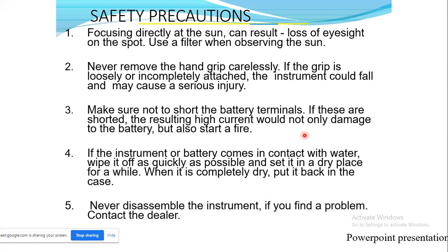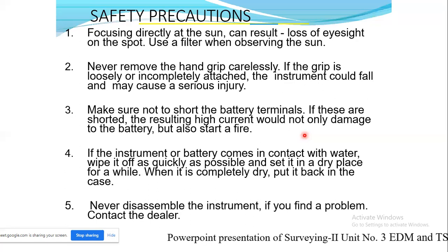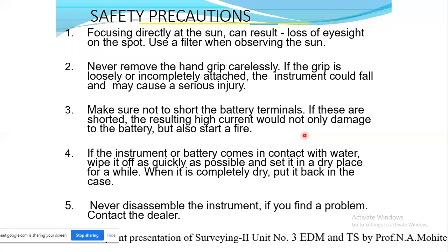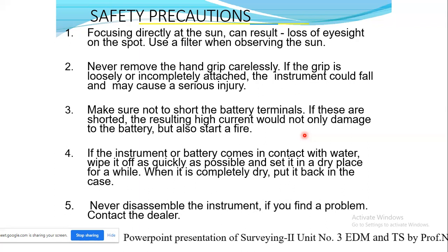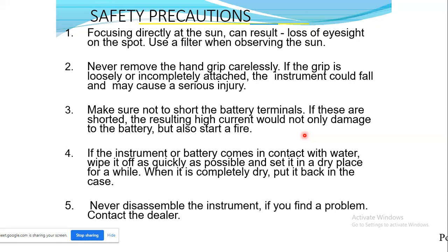Never remove the hand grip carelessly. If the grip is loosely or incompletely attached, the instrument could fall and may cause a serious injury. As I told you, it is a heavy one. One person is going to handle the instrument, and the second one is going to fit it from the bottom.